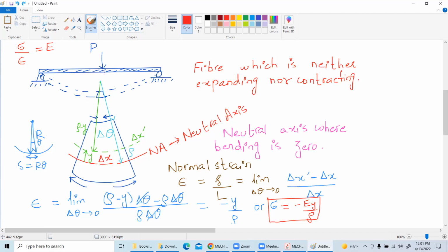You can use that statics principle, bending moment diagrams and shear force diagrams, just to know where the maximum bending moment acts on that beam. That's fine. But our concern is, once I have found that maximum bending moment, I slice it and I want to talk about which section at that point is sustaining the maximum stress. So I will go through my statics, find out the maximum bending moment at this point, good. Then I will take a knife, cut it, and I want to talk about whether the top point has the maximum stress or the bottom point or which point.